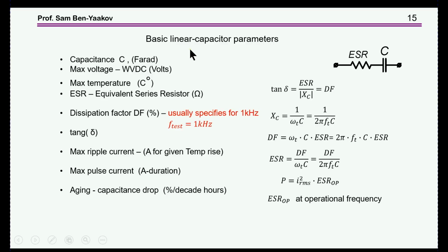What are the basic parameters of a capacitor? Now, I'm here omitting first the inductive part, the self-induction. I'm just showing the ESR and capacitor, and this model assumes that the losses are due to the current flowing through this ESR, which theoretically I'll show is incorrect. The losses are not due to current through ESR. But it's nice, you can do it, and it's been used in the industry and sort of adopted.